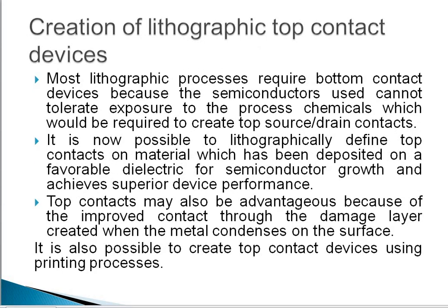Creation of lithographic top contact devices. Most lithographic processes require bottom contact devices because the semiconductor used cannot tolerate exposure to the process chemicals which would be required to create top source drain contacts. It is now possible to lithographically define top contact on material which has been deposited on a favorable dielectric for semiconductor growth and achieve superior device performance.